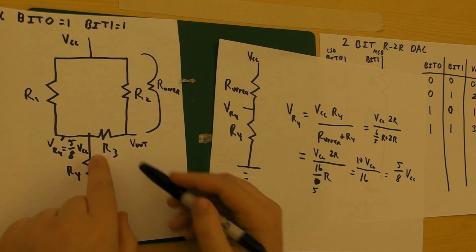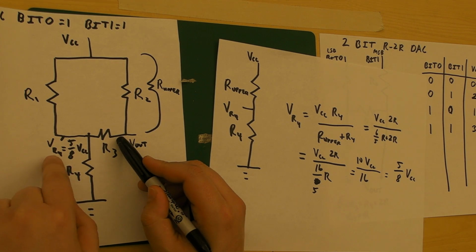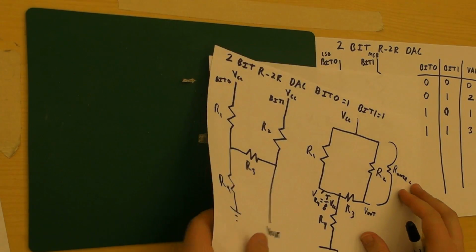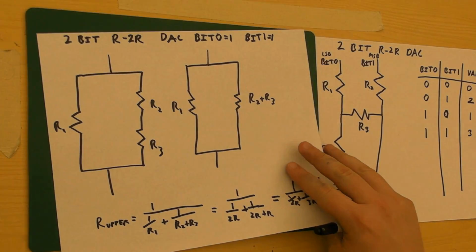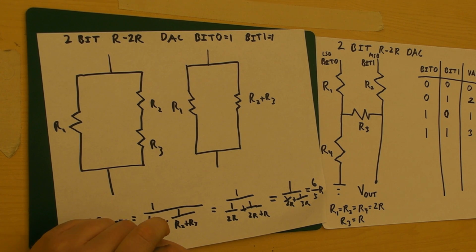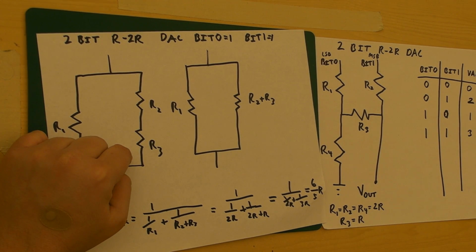Now we have to figure out what the voltage drop is over R3. We can sum that plus VR4 and we're done. Well, fortunately, we've already looked at this circuit. It's here. So we can actually figure out what the voltage should be here. This is just a voltage divider again.